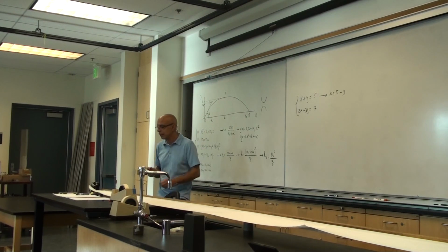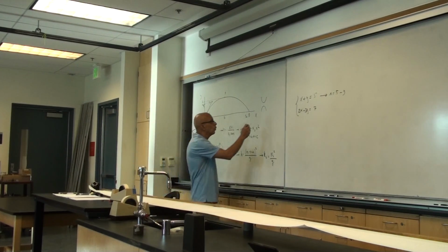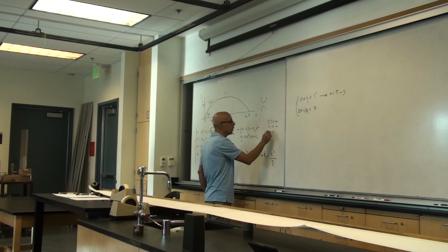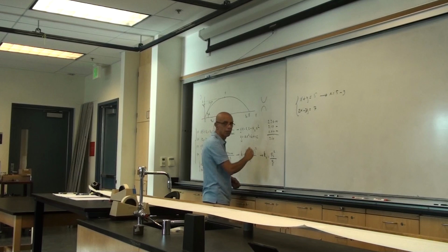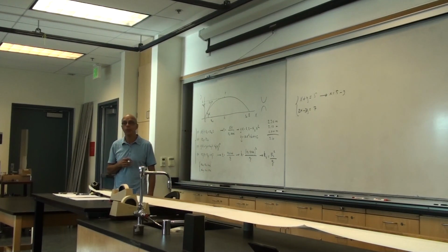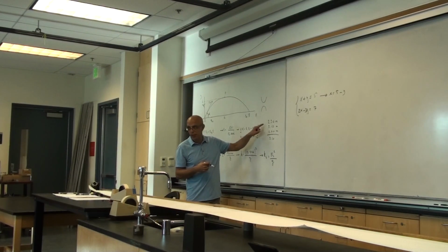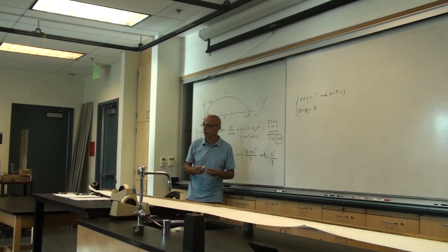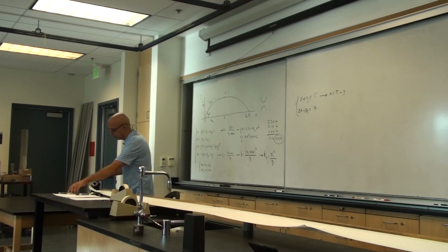So we figured that we had 2.2 meters, 2.1, and then 2 point something, right? So the average here is going to be 2.1. And we need to estimate an error, right? What would be, going plus or minus 10? Let's do plus or minus 0.15. Okay? Now, how much is that in percentage? Let's calculate here.